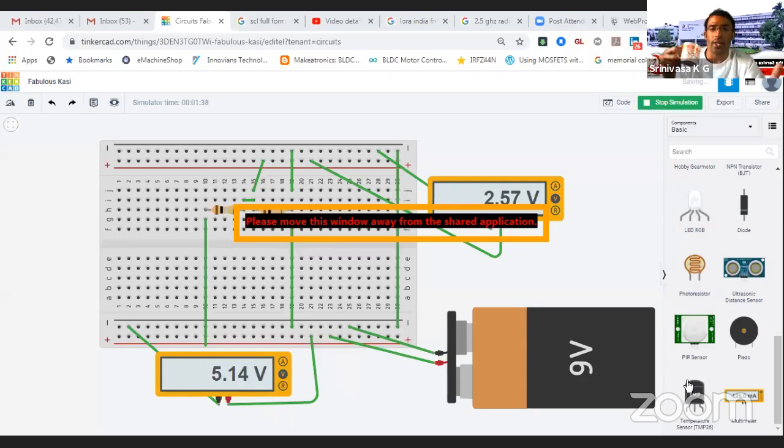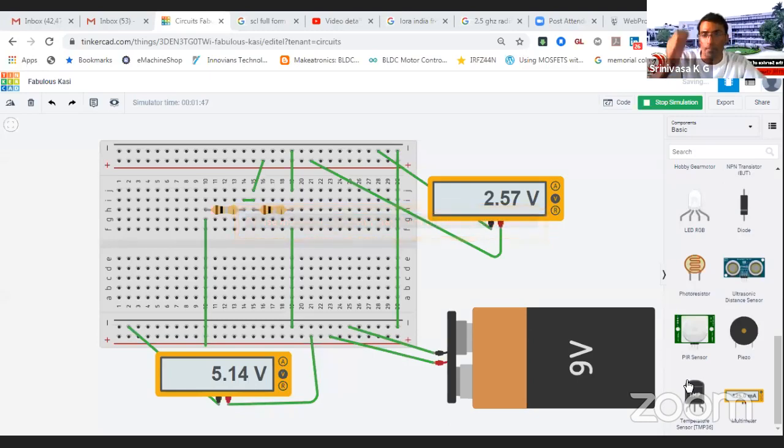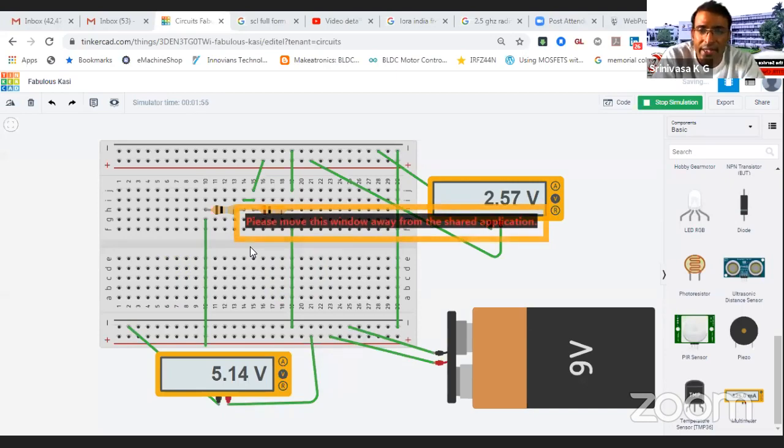So that is a very important concept. Now we are going to use this concept over here. I'm going to repeat it again. If we have to use a voltage divider circuit for any kind of sensor application, then we have to use a 1 kilo ohm to 10 kilo ohm range of resistance, that is optimum, because with the help of that your current loss will be minimal and you will get proper accurate output voltage.